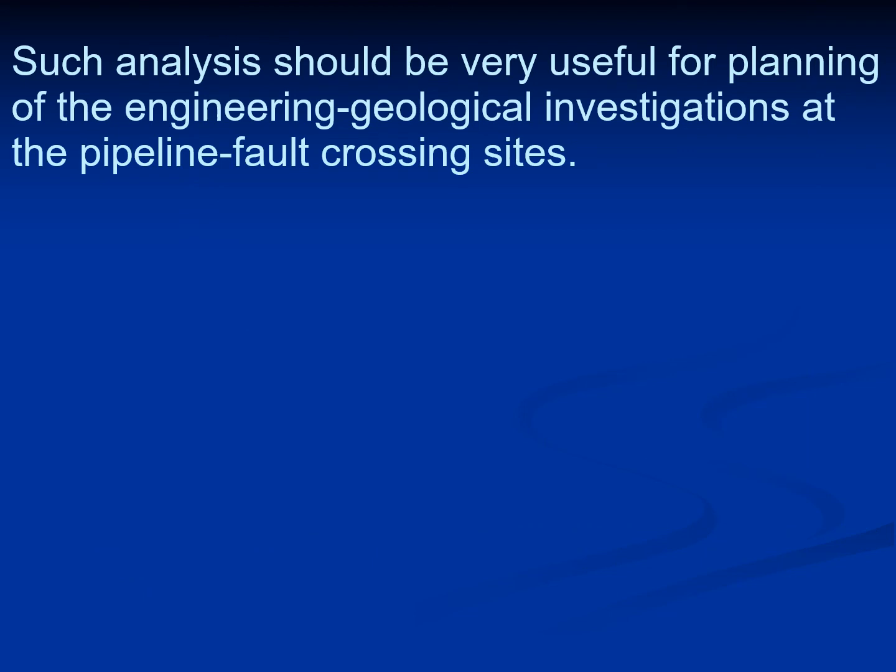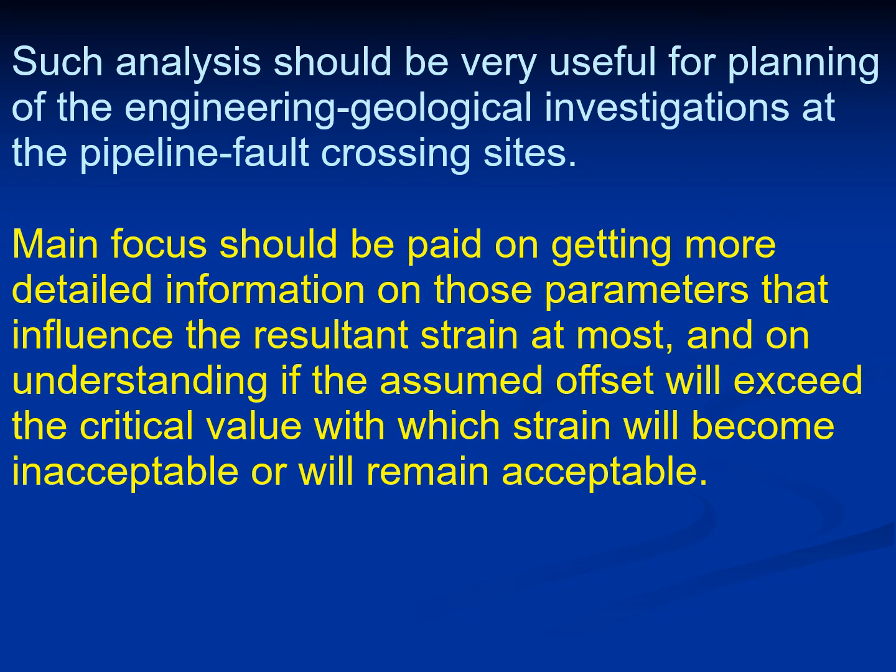And such analysis should be very useful for planning the engineering geological investigations at the pipeline fault crossing sites. The main focus should be paid to getting more detailed information on those parameters that influence the resultant strain in the pipe the most, and on understanding if the assumed offset or fault kinematics will exceed the critical value at which strain will become inadmissible or will remain acceptable.